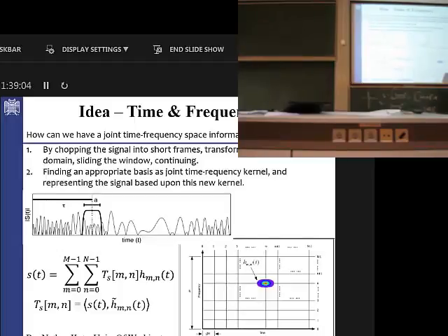So you are trying to reconstruct the signal based on these atoms and the coefficients you have to assign to each of them. For this time-frequency plane, by changing m and n, we can move forward in time or frequency. And we know that these coefficients are nothing but the inner product, or the projection, of the signal over the dual of those atoms. If they are orthonormal atoms, then the duals are the same as themselves.